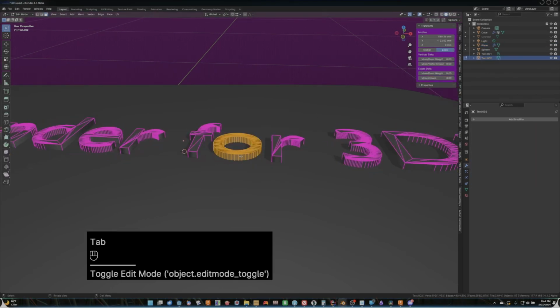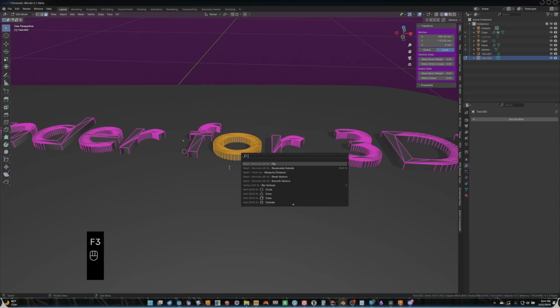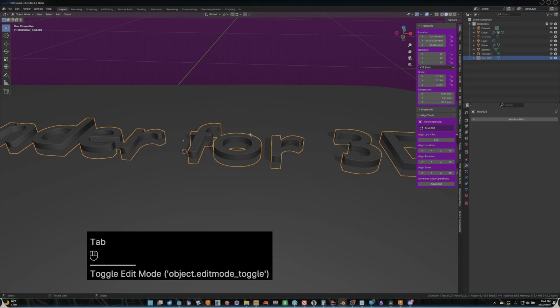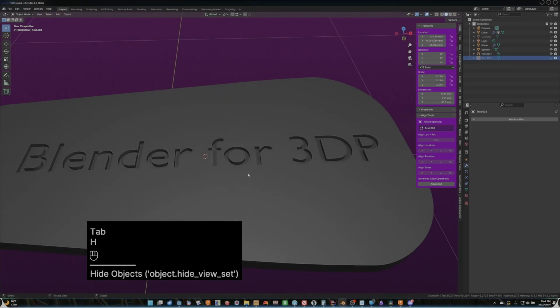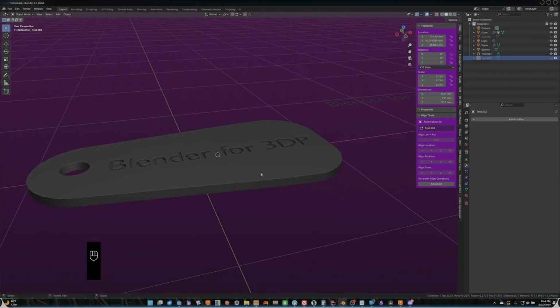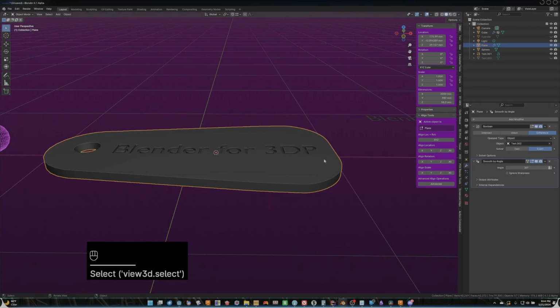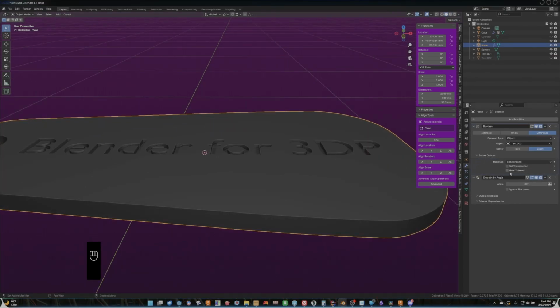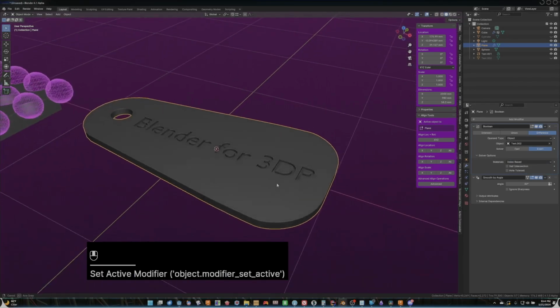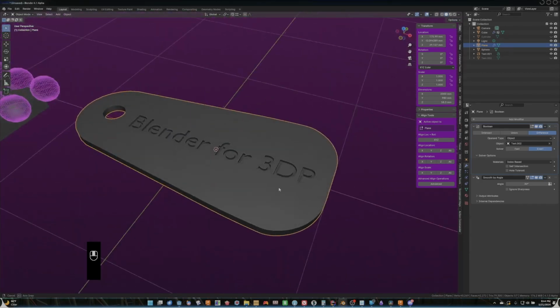It's just flipped normals. F3 activates the fuzzy finder, and then you can just type flip, and we'll hide the text, and it's good again. And we don't need that fast solver. We can use the exact solver and get the results we want. There's also hole tolerance, self-intersection, and then you have some materials options as well. But that is generally the gist of it.